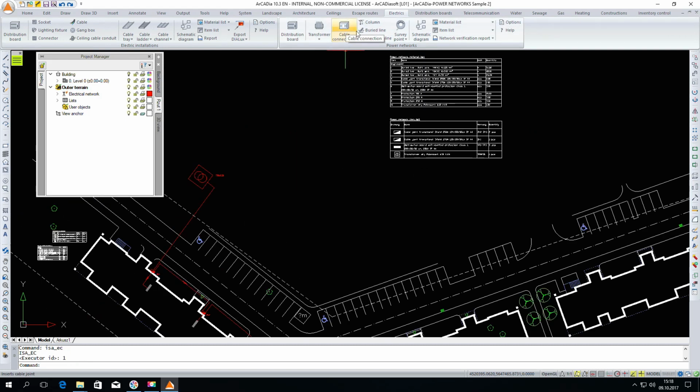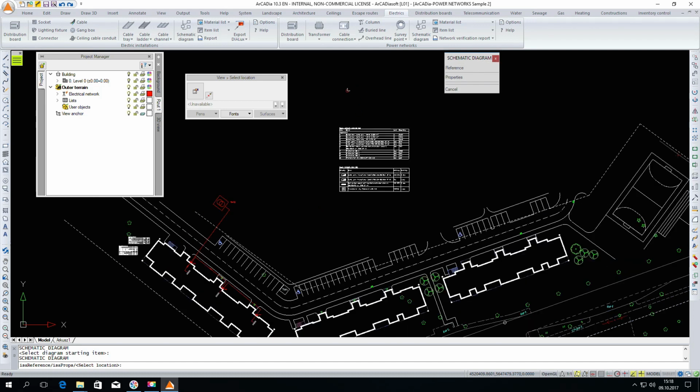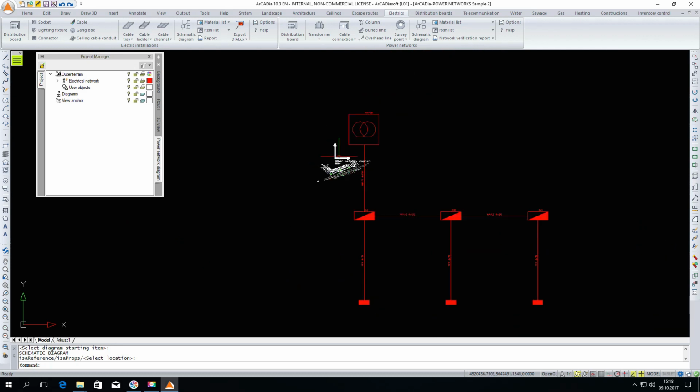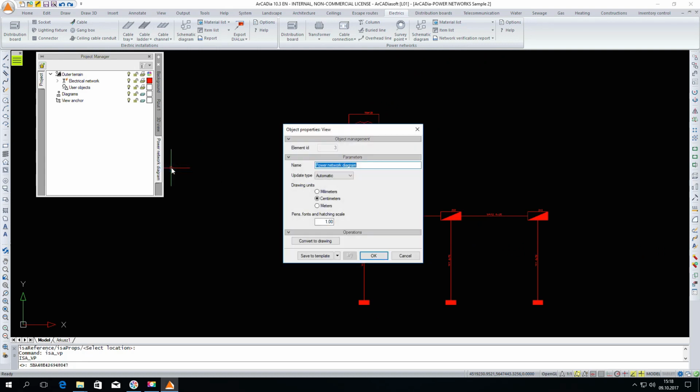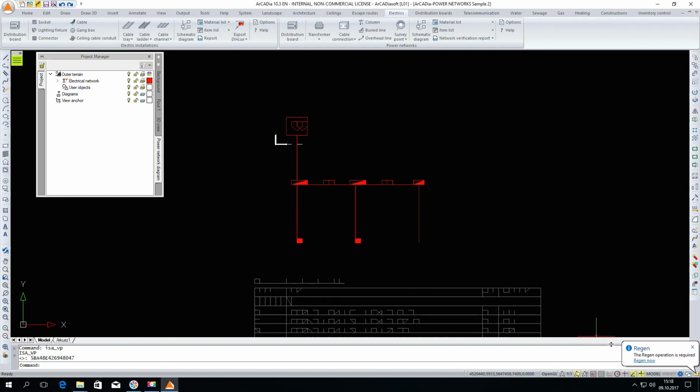Finally, we will generate a network diagram. Mark the start element and insert the schematic. This schematic diagram is at this point inserted in centimeters, that is, in the default unit of the program. We can mark the schematic view and change the unit to meters in this figure. Sometimes we need to do a regeneration, and we have the diagram inserted.